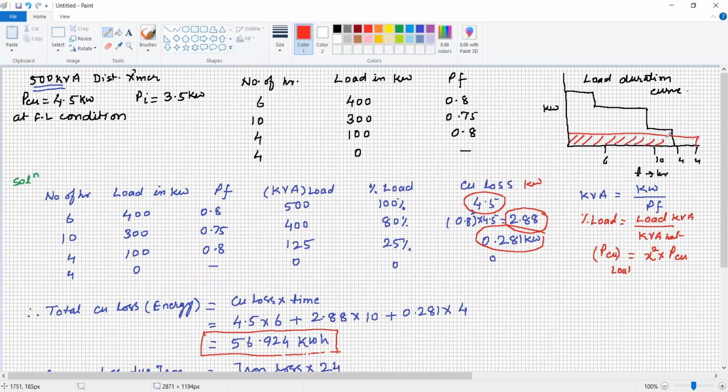Under the competitive market, people design the transformer at somewhat higher flux density, but because of this it gives more iron losses, which remain present in the transformer 24 hours. So it is better to purchase a transformer with low flux density. No doubt the cost is somewhat higher, but over a period of time, because of the energy loss savings, the amount is going to be recovered.